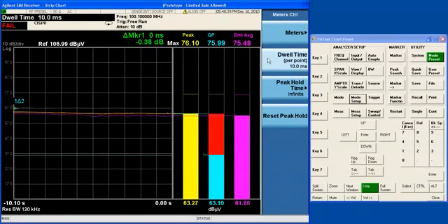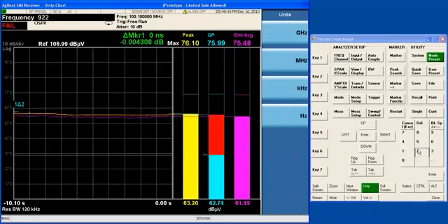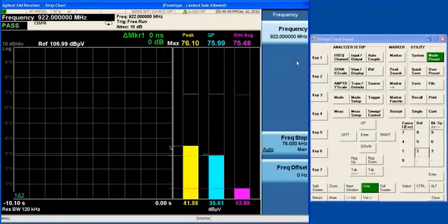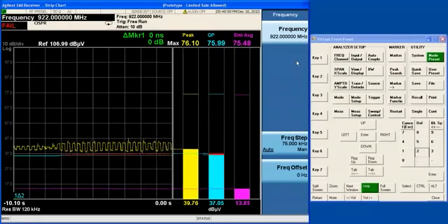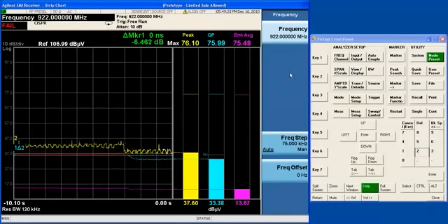In the case of the strip chart, what you're usually trying to do is get an idea of the signal dynamics. So remember when we were at 922 megahertz, we had that signal that was changing really rapidly and demonstrating a lot of the value of the strip chart and looking at signal dynamics. Here we're using 10 millisecond resolution on the meters. We're not dwelling for 1 second. And so we're not taking quasi-peak readings that we would submit as part of a final compliance measurement. We're looking at the dynamics of the signal.